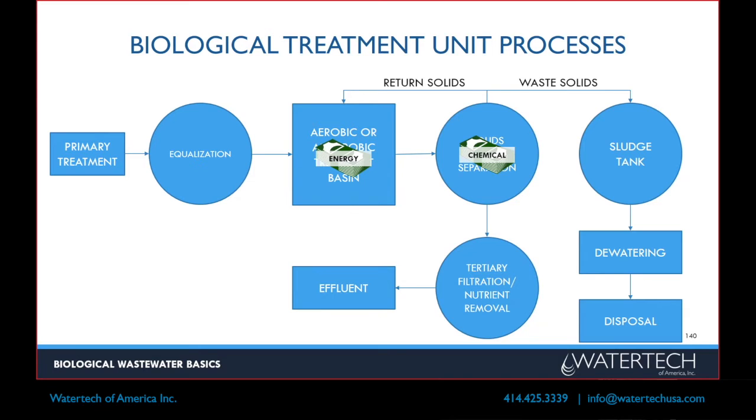On the aerobic side, you're going to have a lot of energy requirements in your aeration basin. You have to blow a lot of air into that tank that I showed you at the beginning. It takes a lot of energy to do that. Oftentimes at a municipal plant, that's their largest cost, just aerating all the different basins that they have. Solids liquid separation, depending on the technology, you'll have some chemical usage there. If you can do gravity separation, then that can be relatively low.